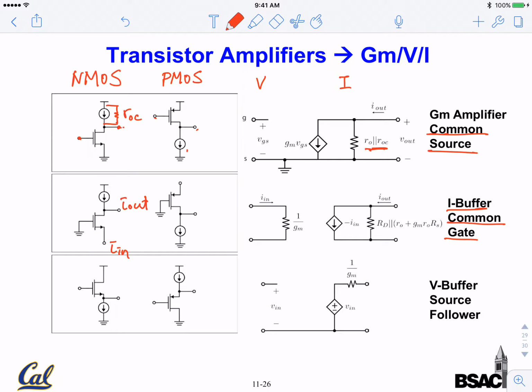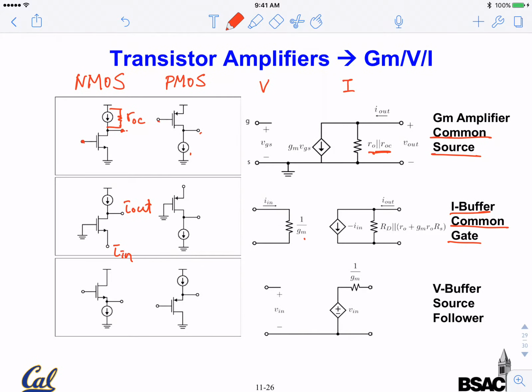There's nothing hanging at the input port, because we have already taken the DC circuit out. So the I in goes into the input resistance, 1 over GM, and it goes to a current gain, which is -1. So AV is minus AI. AI is -1.